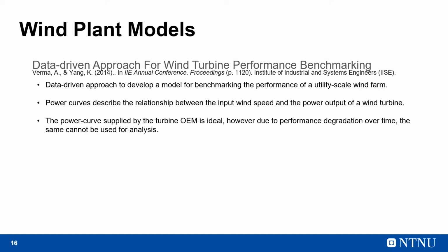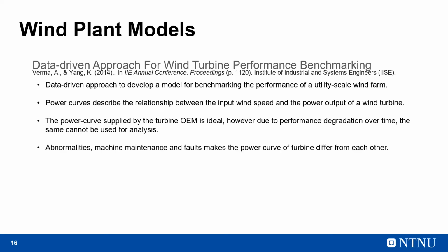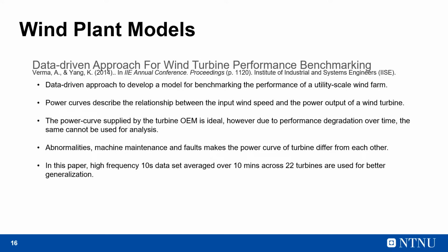The power curves supplied by the OEMs are ideal, but since the turbine performance degrades over time, you cannot use the same power curve, say, after 5 years. Abnormalities, machine maintenance, and faults make the power curve of each turbine differ from each other.